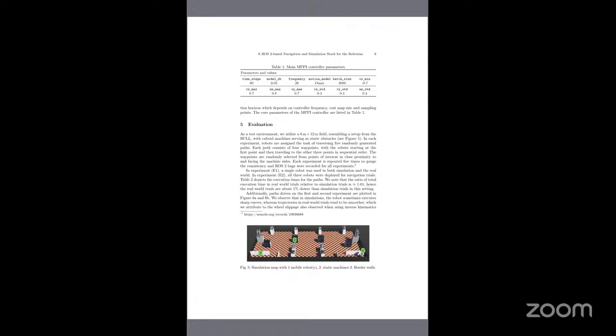As per table 2, the simulation to real robot execution time ratio is 1.01. That means the real robot takes about 1% more time. So this ratio represents that the simulation is almost exactly mimicking the behavior of the actual robot.